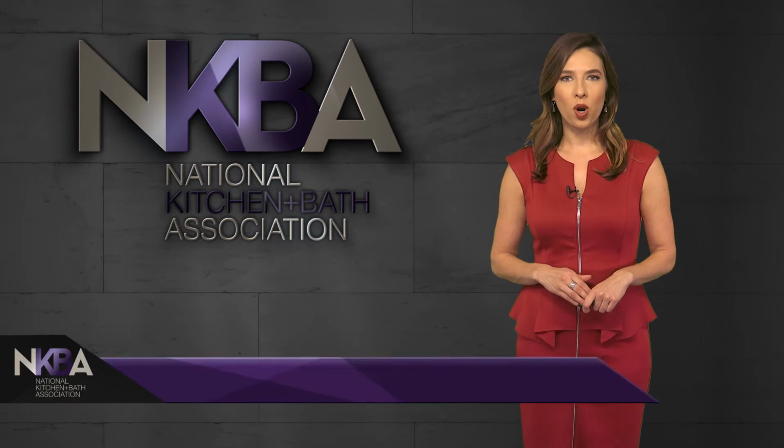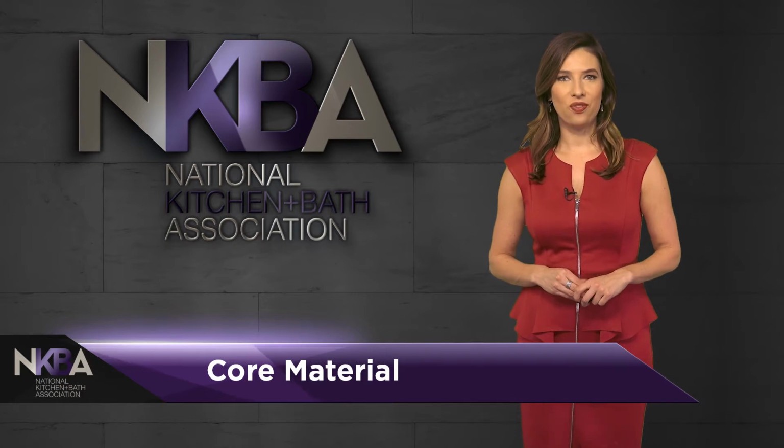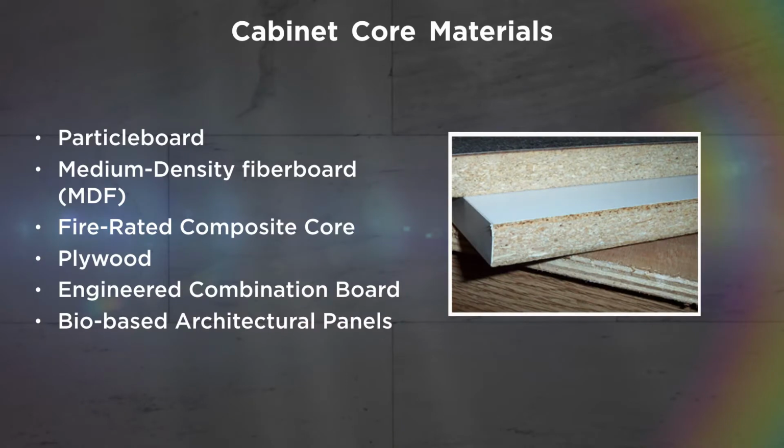It's time to talk core material. That's the stuff in the middle of the cabinet that is covered up with the nice finishes. Core material comes in 6 categories. Particle board and MDF, medium density fiber boards, offer great stability. A fire-rated composite core is available for commercial applications. Plywood gains its strength by alternating the direction of the layers of thin wood. Engineered combination board combines the attributes of both plywood and particle board. Bio-based architectural panels are made of recycled wheat stalks and are often referred to as wheat board or agriboard.